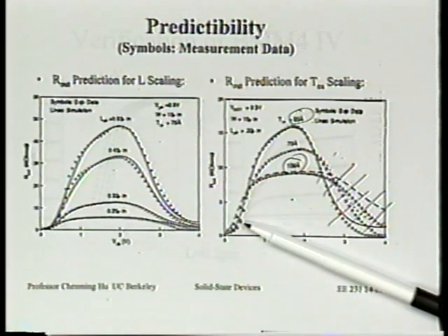And if we don't like the DIBL effect, first of all, let's remember, DIBL effect is something we don't like. It's a bad thing. We want to suppress it. One very effective way to suppress this bad thing, this VT roll-off, this DIBL effect, is to make the oxide thin. Remember that conclusion? All right. So thin oxide will suppress the DIBL effect. So in a thin oxide device, the DIBL effect is weaker. All right, your comment.